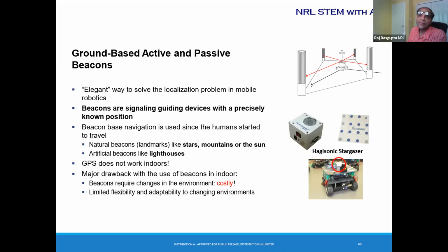If you come to the PiMars lab, which Vijay runs, you'll be able to see a setup there that has some beacons placed on it. So beacons are basically ground locations which have a fixed location, and you can calibrate any sensors, basically the robot, against it. It's a well-known point. So when the robot goes closer to that, it knows where it is.